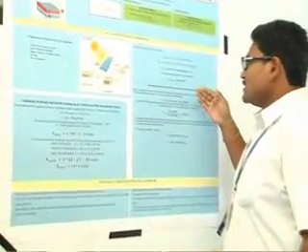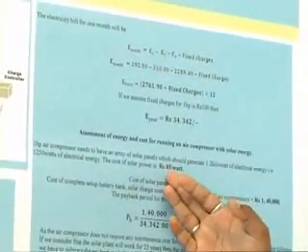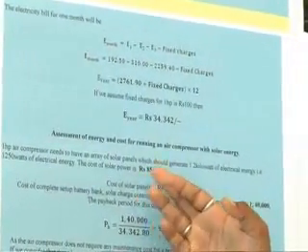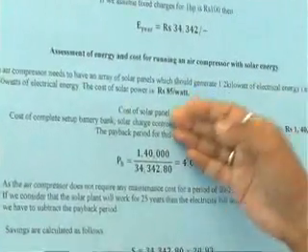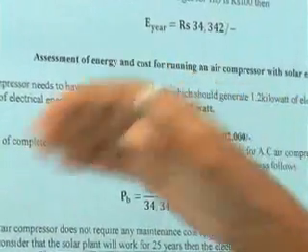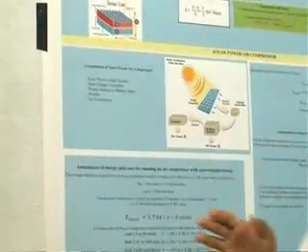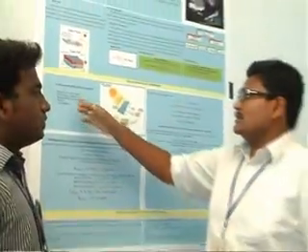By using solar power, which is now available in India at rupees 85 per watt, for 1.2 kilowatts you will be charged around 1,02,000. But solar power gives only DC power, so the DC power should be converted into AC power. That conversion is done by an inverter.